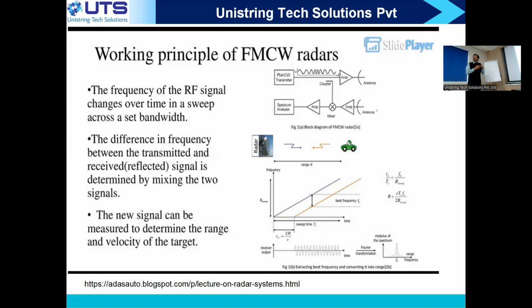What does it mean? There is an echo which is at 150 meters. We did calculations of why 150 meters. Because it is at 150 meters, my received signal has the frequency from 1 microsecond earlier, which is 1 megahertz. That's why when I'm mixing these two, I'm getting a 1 megahertz component. So that is the principle of an FMCW.